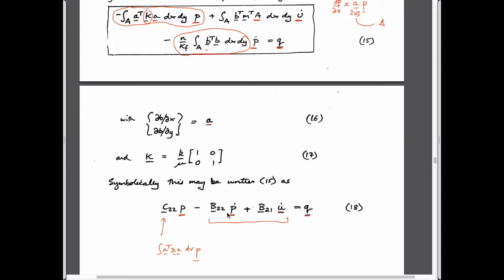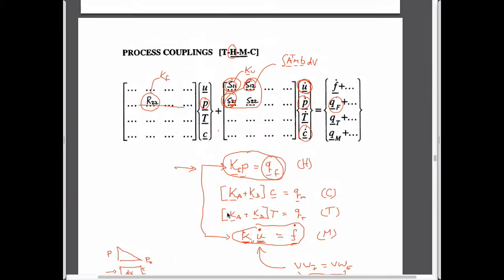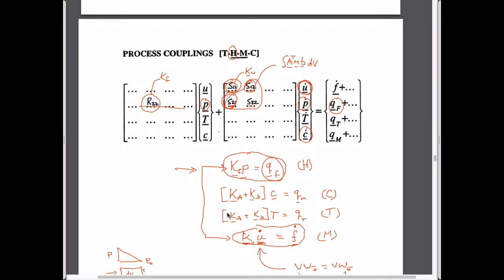And so, as I said, the key really is being able to figure out exactly what the magnitudes of these cross-coupling terms are. It's kind of messy here, and I can't go back to it particularly, but you'll see that the solid equation has normal F equals KU in it, but a coupling term, and this coupling term is a body force. The flow matrix has a term which relates to normal Darcy flow through nodal values of fluid pressures linked to flow rates.